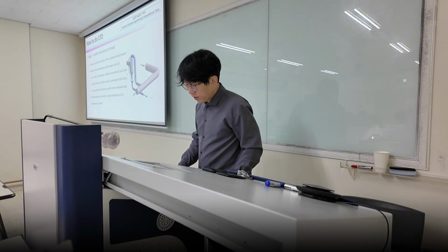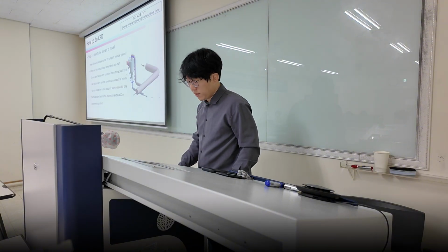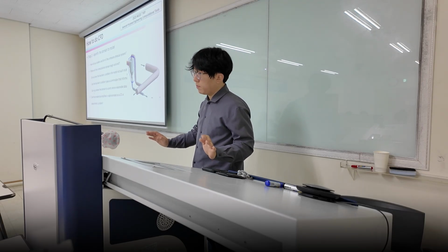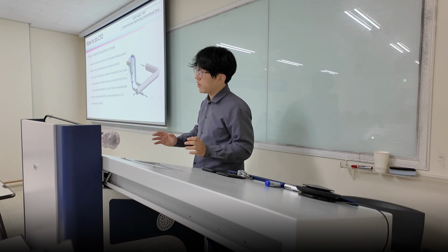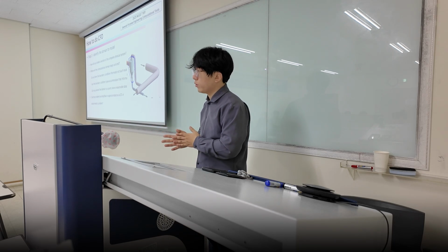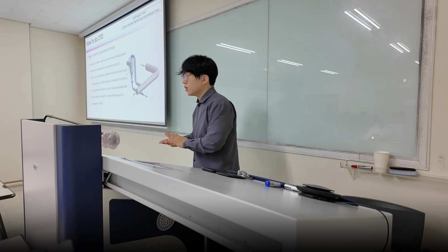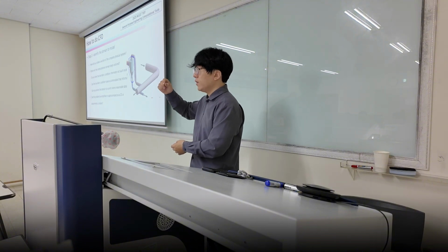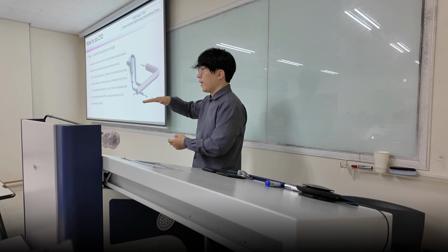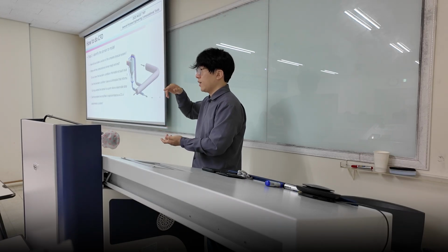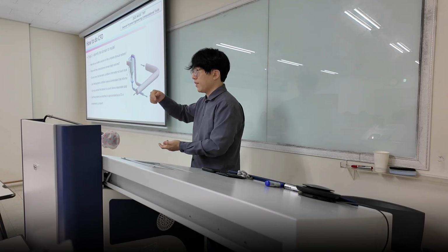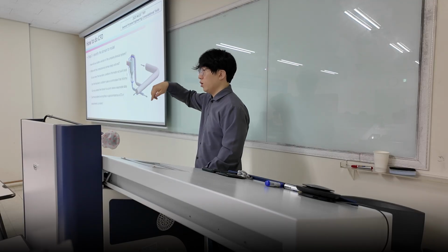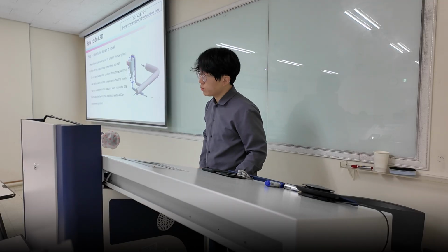And as you can see here, make sure you understand if you can simplify the problem into a two-dimensional axisymmetric problem. So what happens with, for example, two-phase flow is it's largely axisymmetric, so it's radially different, but in the angular direction, it has the same phenomena over the axis. So that's one approach you have.